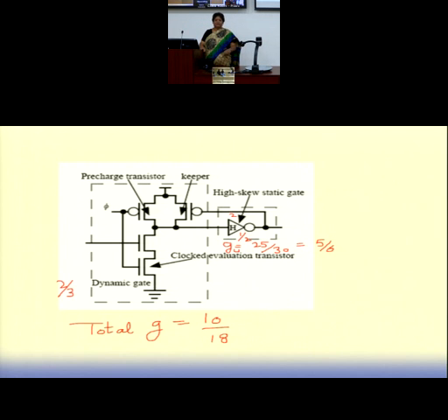You don't have a series of parallel combinations. So that delay in itself is also very small. Even if you make it weaker, the pre-charge delay will increase, but not by a tremendous value. It's a very simple block, one charge transfer. No series combinations over there. Series combinations are happening only in the pull down, which can cause the delay to increase.